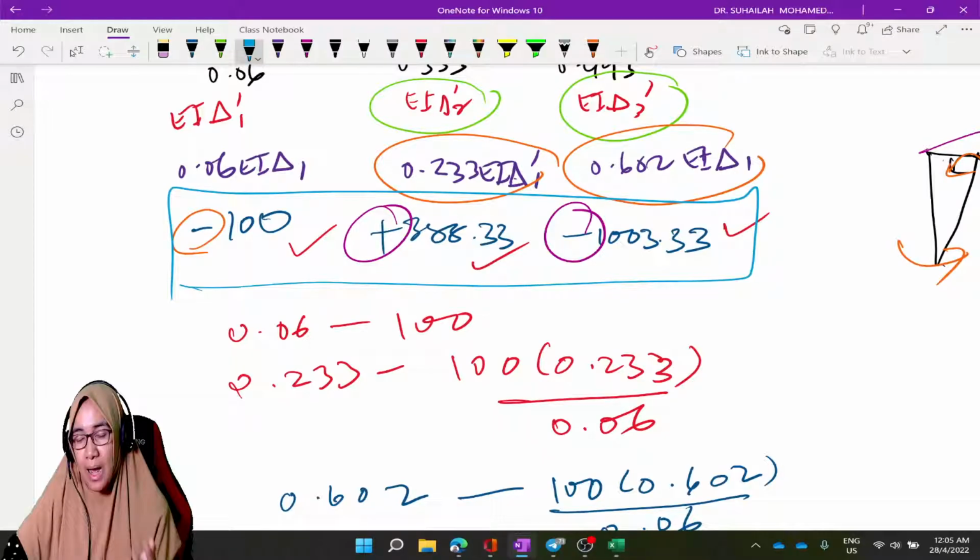So we have to apply FEM for all members, because in this case delta is not constant. We have delta 1, delta 2, and delta 3 for AB, BC, and CD respectively. So we find by using ratio, and compare with 100, the first FEM assumption, and find the remaining ones using calculation.